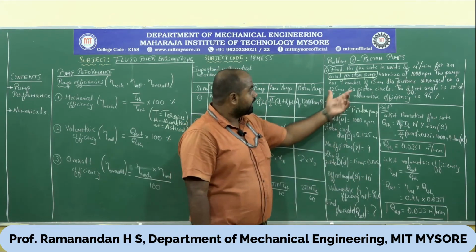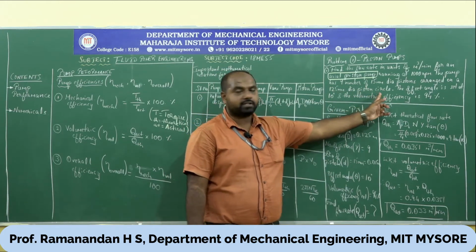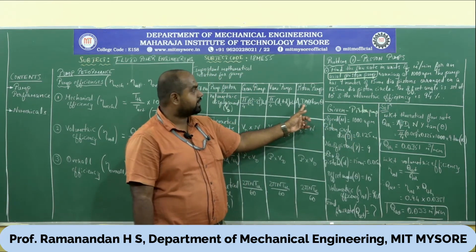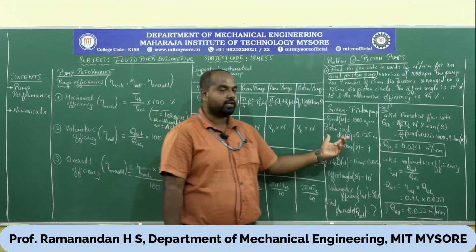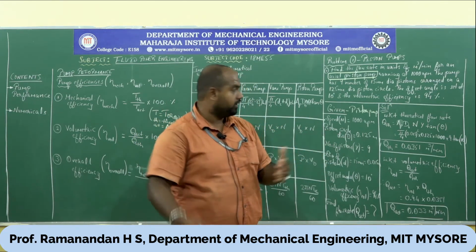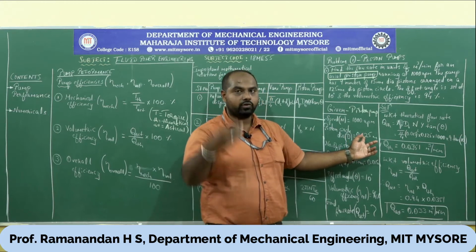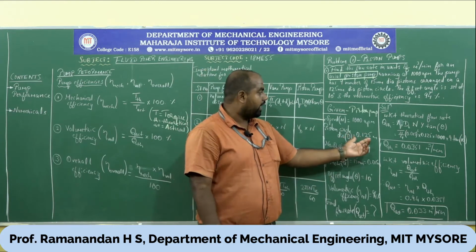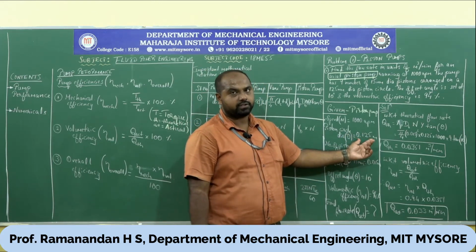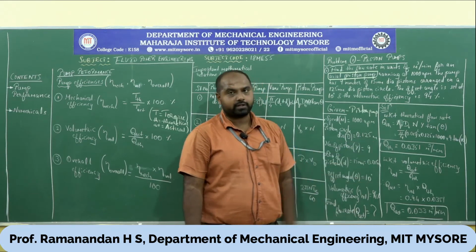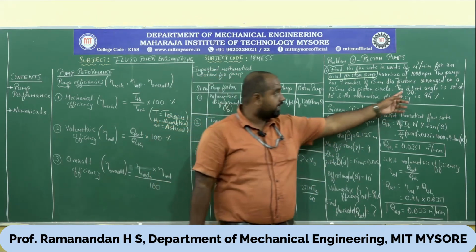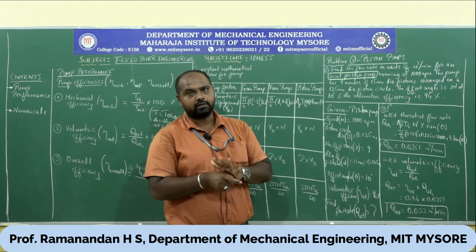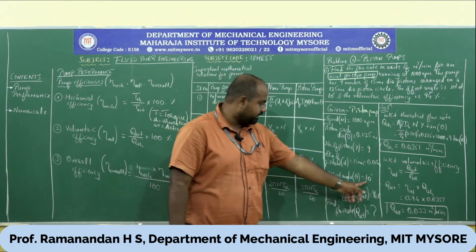Then comes, arranged on a 125 mm dia piston circle. He has given the piston dia circle, that is the indication of d_B. He has given cylinder bore diameter 125 mm. Millimeter, again I have told you, divide by 1000 or multiply by 10 to the power minus 3. Milli is 10 to the power minus 3. So 0.125 meter. The offset angle is set at 10 degree. Theta is the offset angle, that is the swash plate angle of piston pumps. So theta is 10 degree.